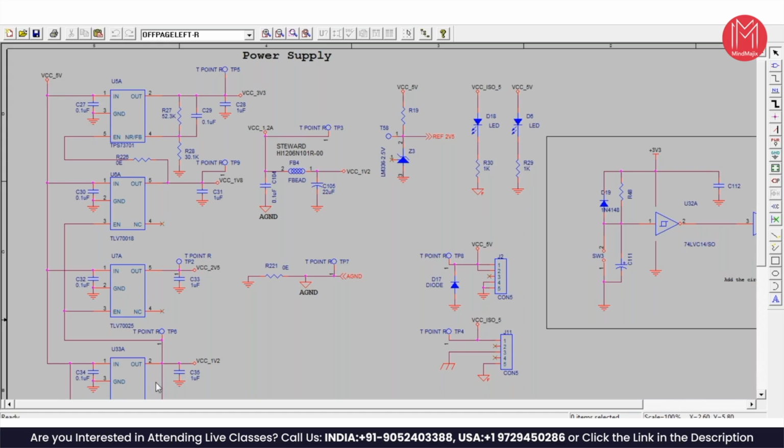Once the 1.2 volts is stabilized, the 1.8 volts gets stabilized. Once the 1.8 volts gets stabilized, the 3.3 volts. This is called power sequencing. Of course, in the microcontrollers we have discussed it ahead of time, so there is no problem. We'll come back to that. VCC2, V5.